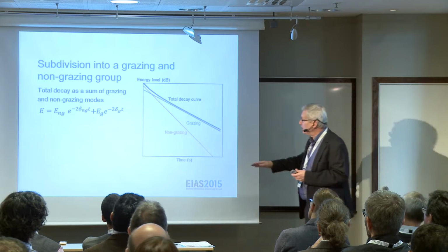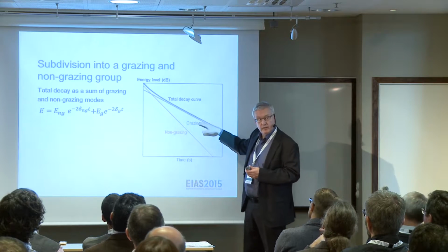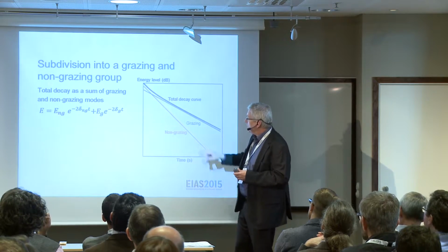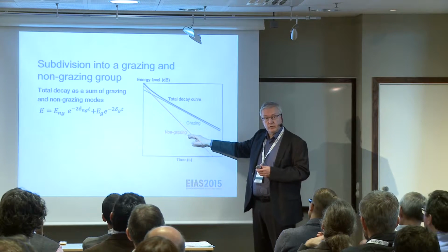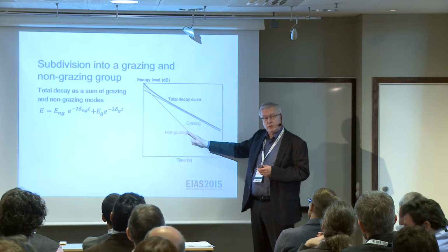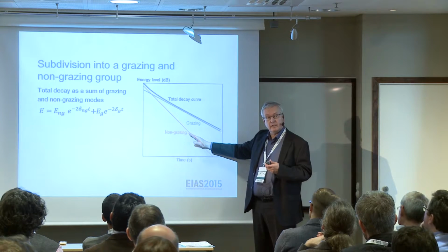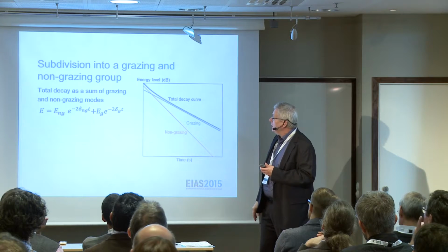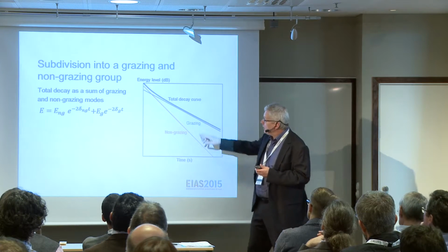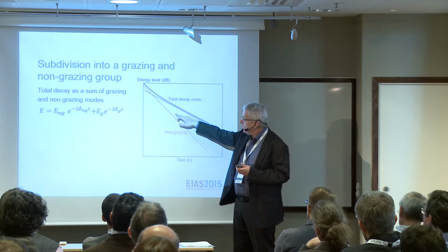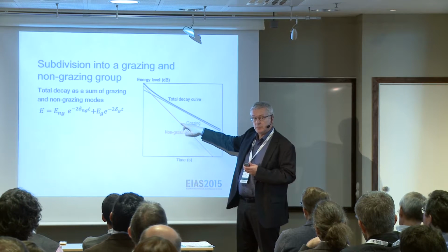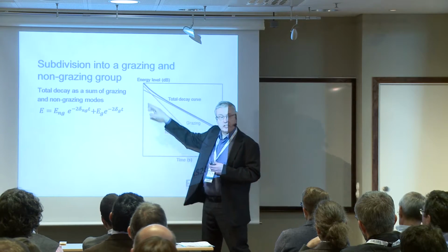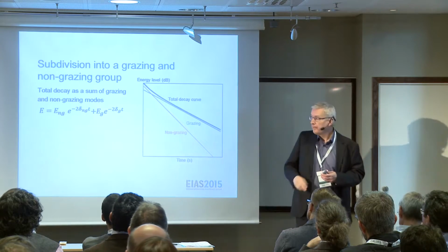One part dealing with the late reverberation time and one with the early part, calling them grazing and non-grazing waves. This non-grazing part, we can say, corresponds a little bit better to the Sabine assumptions than the grazing. But here, of course, we have to estimate the decay factors for these two slopes. But not only the decay factors, you also have to know the energy to get the strength value.